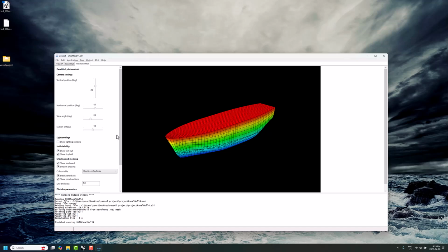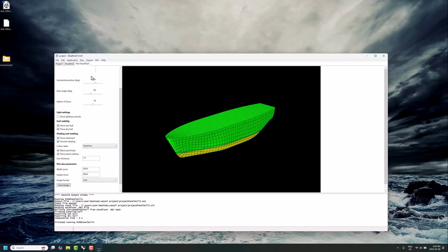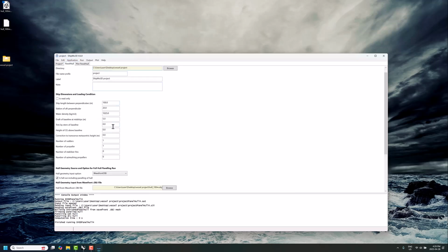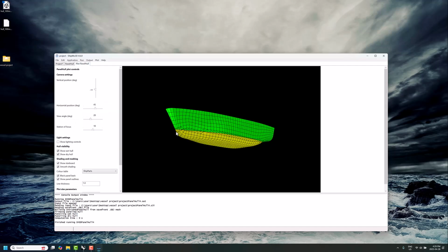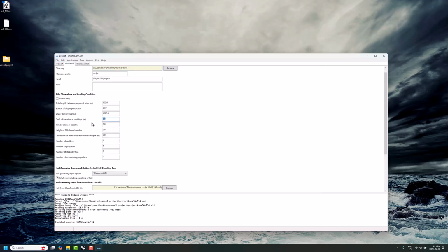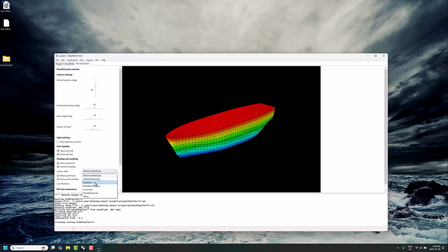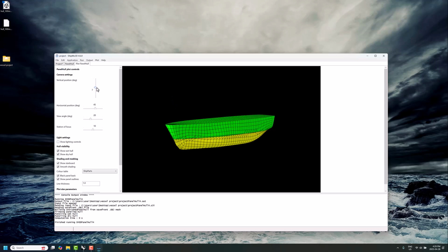So we got plot panel hull and go ship parts. Now we have the yellow part showing as the displacement. Remember when we bumped the hull orientation, so the baseline was at the Z plane. The reason for that is because we may be changing the displacement when we're doing the hydrodynamics analysis. And with a 5-meter displacement on this 100-meter long hull, you're seeing the yellow form here is the wet hull, and there's some automatic mesh refinement along here. So ahead of doing this analysis, you may realize, oops, I meant to do 8. Rerun this again. And so you'd be adjusting that displacement. I really like the ship parts because it just very clearly shows which is the wet hull here.